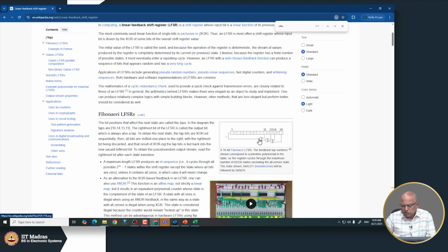And from a layout perspective, you will possibly appreciate that the Fibonacci LFSR which you are seeing here may be a little bit more difficult than doing the Galois LFSR. The Galois LFSR will have a sort of regular layout. We can have 2 types of cells, and we can just place them side by side and make near neighbor connections.